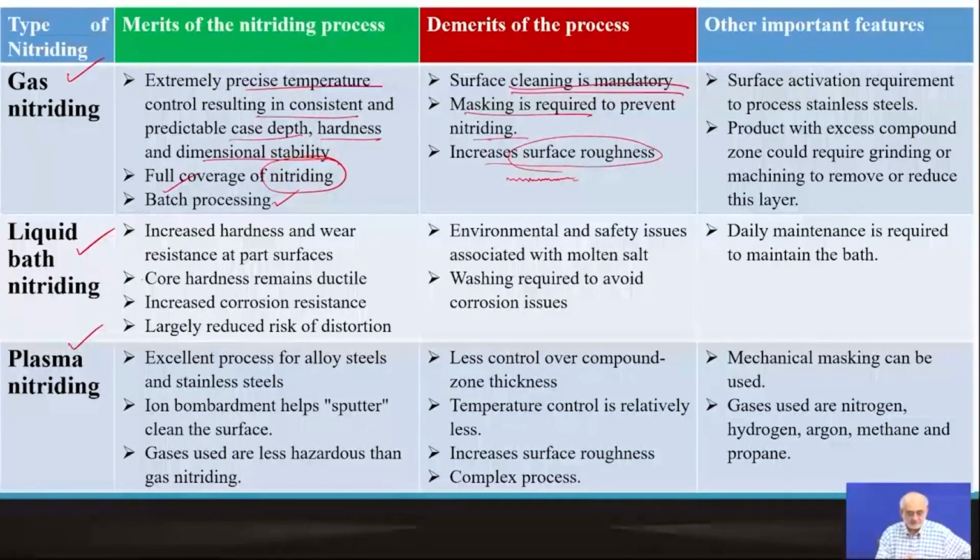If you go to liquid bath nitriding, you have higher hardness and wear resistance. The core hardness remains the same, so you're not affecting the core. The corrosion resistance improves, which is true for any other nitriding process also. And because of the slightly lower temperature and a liquid bath, the temperature is maintained very uniformly and distributed, so there is less risk of distortion. So these are all good points.